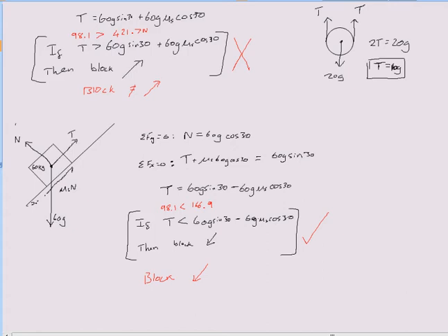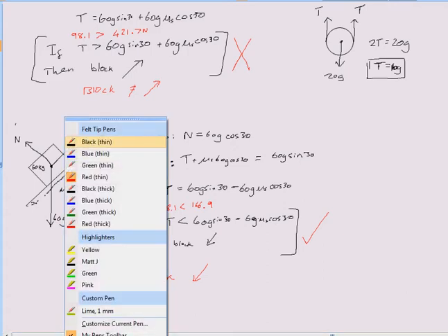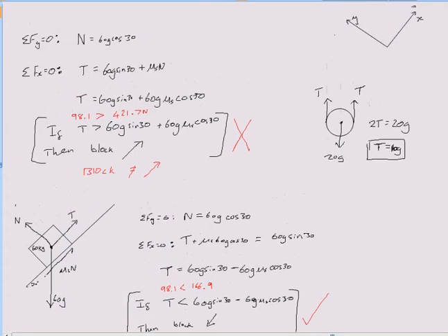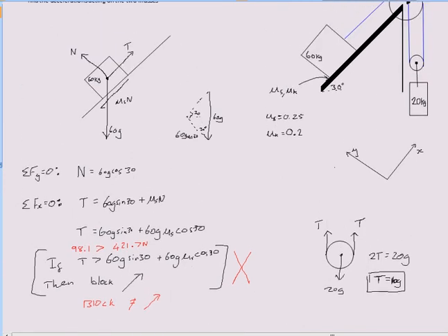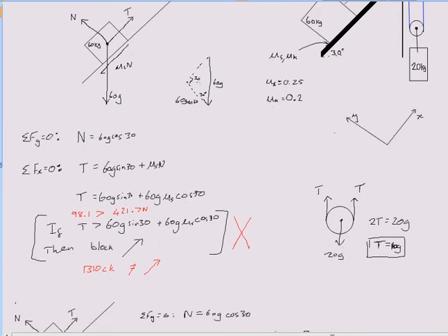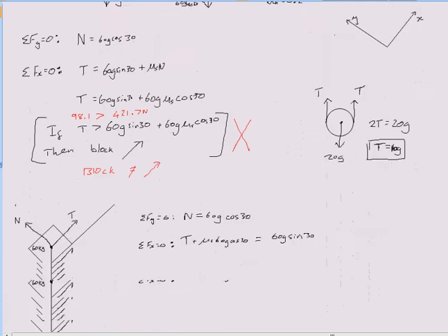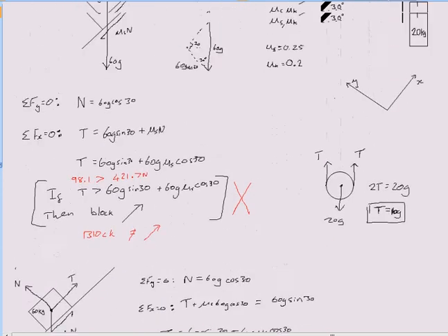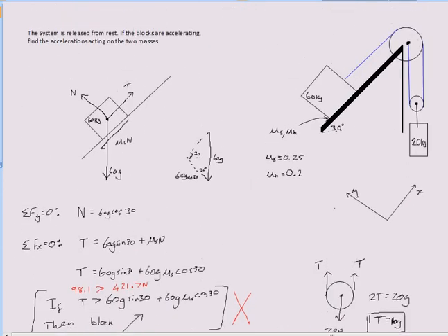Anyway, so we're halfway through the problem, and we've done the most work. From here on, it gets a little bit less tricky. But now that we know the block's moving downhill, we can actually redraw this particular free body diagram, knowing that because the block is moving downhill, you're going to have a resistance force acting uphill at all times.